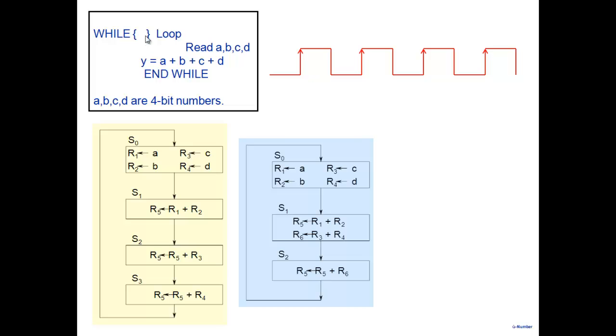I can take the same description and now talk about carrying out that particular computation like this: S0, S1, S2. What is the difference between the two? Two adders, but what do I gain? By the way, what is the latency here?